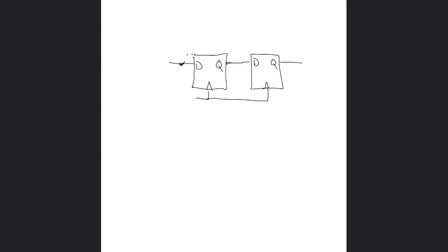Right, when we get a clock edge here, whatever is present at this point will be copied and put onto this point, and it will be remembered. That clock edge is going to clock that value through onto here, but because it's synchronous, it's also going to take this value and put it here. So as soon as the clock strikes, two things happen. This thing is copied here, and whatever was here is copied here, which has the effect of shifting. Do you agree? Yes, sir. Okay, I understand this.